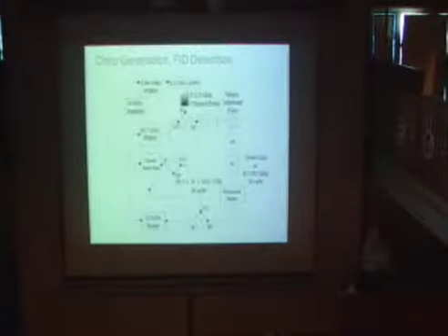This is our chirp generation and free induction decay detection system diagram. We generate a low frequency broadband chirp with an arbitrary waveform generator and mix it with a 10 gigahertz fixed frequency local oscillator, and use a single sideband filter to choose the upper or lower sideband of the mixed signal. We send it to an active multiplier chain, which not only multiplies the frequency but also multiplies the bandwidth.